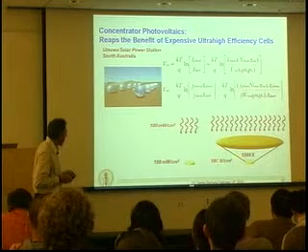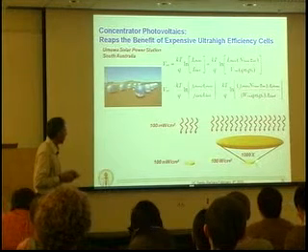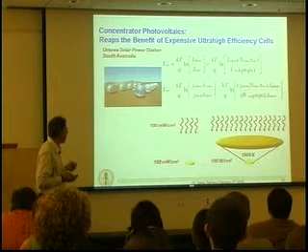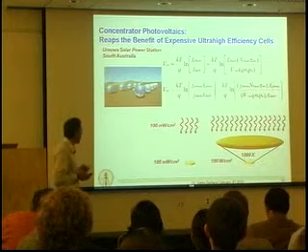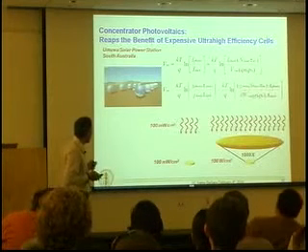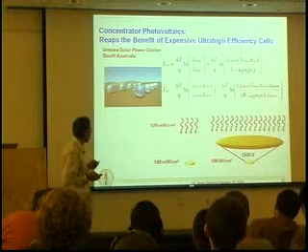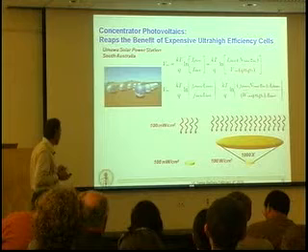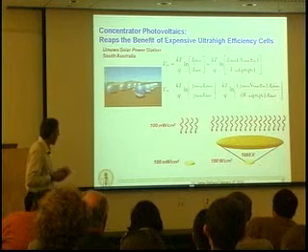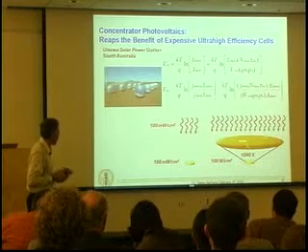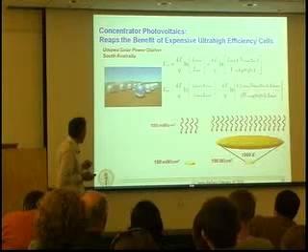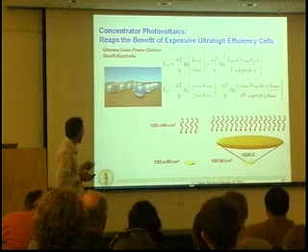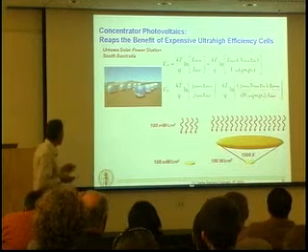One of the things that happens is there's a big change in the power density incident on the cell. And that has an effect fundamentally on the efficiency. If I have some fixed recombination process and fixed temperature in the cell, the open circuit voltage of the cell is proportional to the ratio of the photocurrent to the dark current in the cell. And roughly speaking, it's the ratio of the area of the optical aperture to the cell in this concentrator. And this voltage can increase logarithmically, as the thermal voltage times the logarithm of this concentration factor.